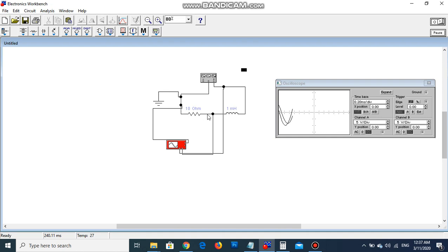Why do I need to measure generator and resistor? Because our goal in this experiment is to compare the voltage of the generator with the current, and since UR is proportional to I using Ohm's law, we observe the two voltages of the resistor and the generator and then we can compare them.